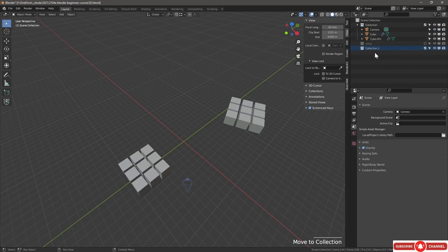To move objects into different collections, we click and drag them in. We can click and drag select multiple to move them into different collections. Collections can be infinitely nested, so we can put that collection back in there. We can also change the order of collections. I have a setup one here that I use, and I'll move that one just above this collection here. If we don't want this, we can move these to the parent collection here. We can also rename all objects, so collections and objects alike. Let's call this geometry.